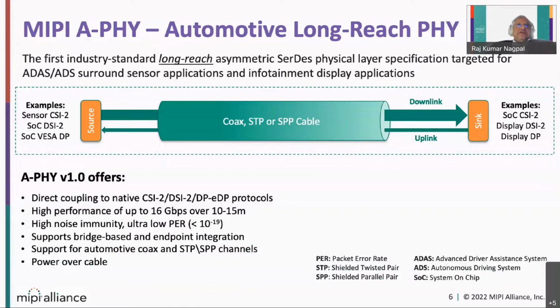It is a point-to-point interface wherein you have a source which can be connected to camera or display sensors, and similarly a sync, which can be a display or ECU kind of thing. It is a long distance physical layer with multiple interconnect possibilities, supporting both downlink and uplink.